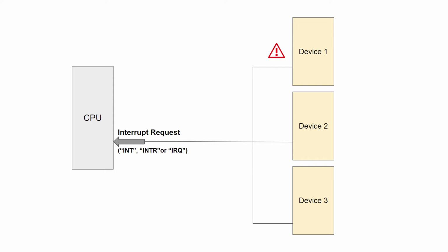The processor recognizes the activated pin and interrupts, hence the name, executing its current program and starting a procedure called interrupt handler. It is a special program to talk to the device needing attention in order to receive or send the data the device needs to exchange. When this handler finishes its work, the CPU returns to the previously interrupted program.